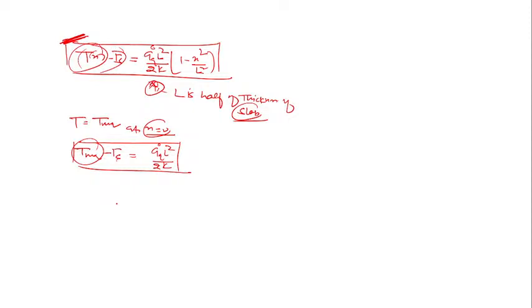If non-uniform heat generation is there, then q is a function of x, and you can't write this. Is this clear? And it is valid where symmetrical boundary conditions are there. If these conditions are satisfied, then only you can use these equations. Otherwise, go for the basics. Clear?